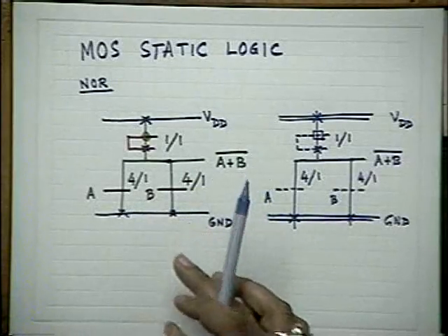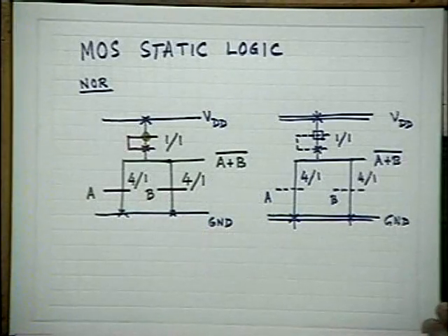Can you tell me, if such a circuit is in the output stage, how do you select the value of W? Suppose 1 micron is the channel length assumed for the particular technology. Now, there are two: one is the logic circuit, which is internal, intrinsic, whereas there will be something at the output called a buffer. In that case, how to choose a value of W? I said L is fixed, 1 micron. W? How to decide that?